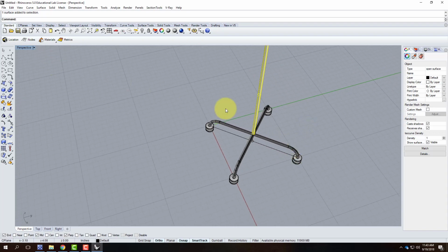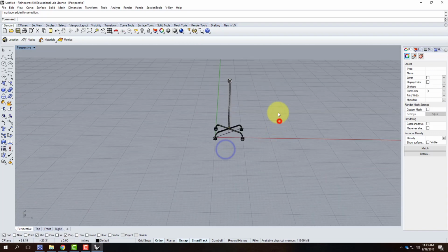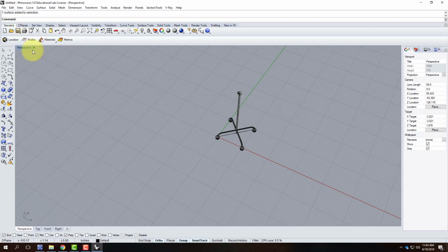So now that I've created this part of it, I need a couple more things. One, I need a sheet of glass, and two, I need the cable that's going to go from this. Now, I should also point out that typically when they're using this as a structural system for a big wall of glass, the cables have to go in both directions. You can't just go in one direction because you have to be able to handle the load going the opposite direction too. So this is not really a real technical wall. It wouldn't actually work, but that's okay.